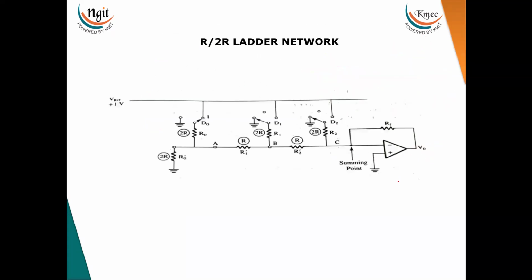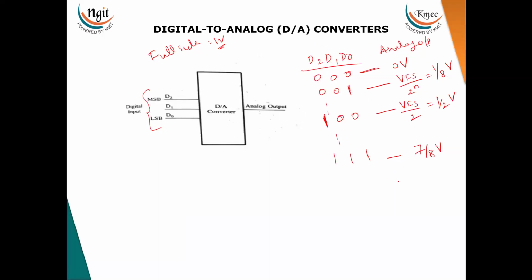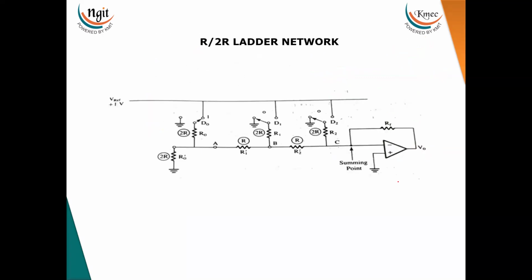This expression we derived in the basic electronics theory class in the last semester. Now, mostly these ICs are designed using the R-2R ladder network, because here only two resistor values, R and 2R, are used. The circuit is designed in such a way that the total current IT is directly proportional to the combination of digital values given here. The digital values are set, and depending upon that it will generate the total current. And this current will be converted into voltage by using the operational amplifier.